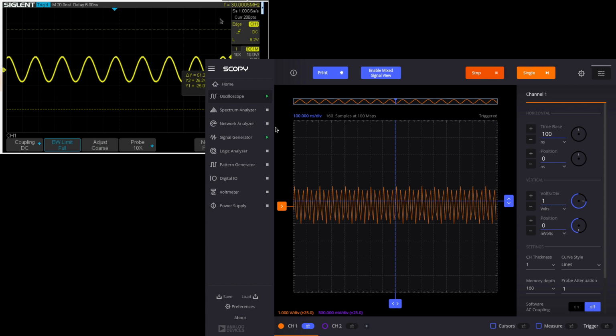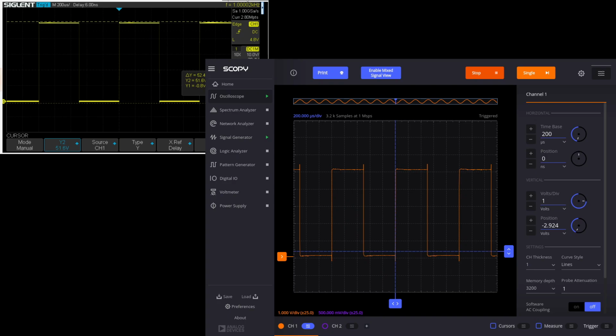One reason for that is that supposedly its DAC, its digital to analog converter, is running at 75 megasamples per second. So, at 30 megahertz, that's not very many samples. But, 10 megahertz looks pretty good with sine waves. Square waves will be more challenging. So here's a 1 kilohertz square wave. Notice that I've used the M2K signal generator to set the base of the square wave at 0 volts now. One thing I don't understand is the little glitches we're seeing on both edges of the M2K display.